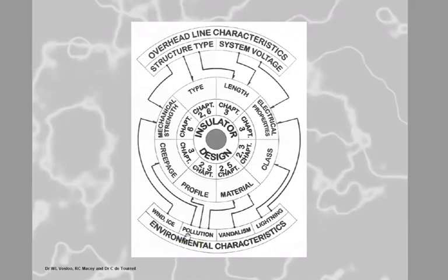And so pollution affects the creepage distance. The creepage distance is the distance from the live end all along the insulator surface, the shortest distance on the surface to earth. So they talk about the creepage distance. Okay? And then the profile of the insulator is what the sheds look like. Do they have an under rib? Or do they have a flat, open aerodynamic profile?